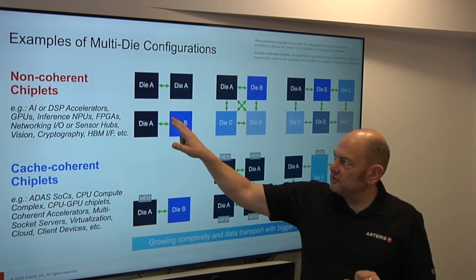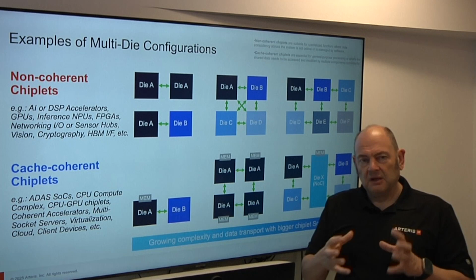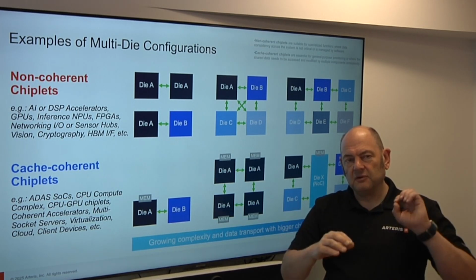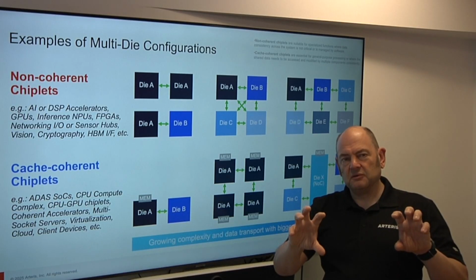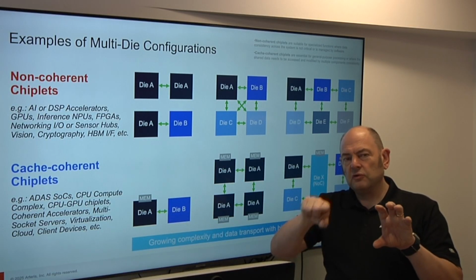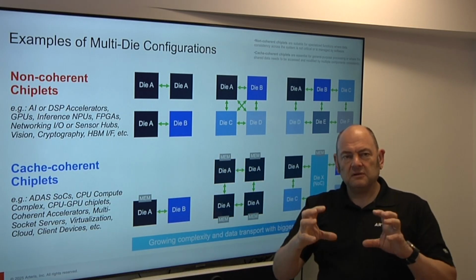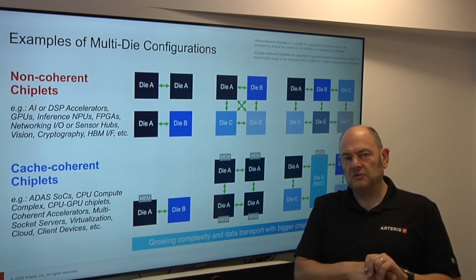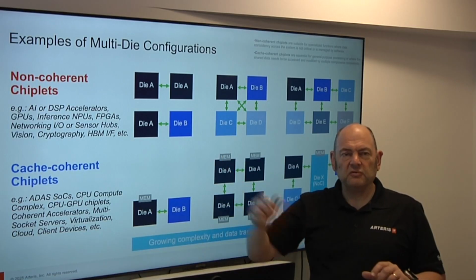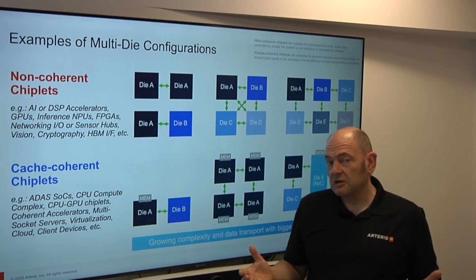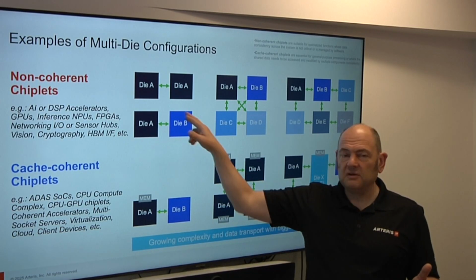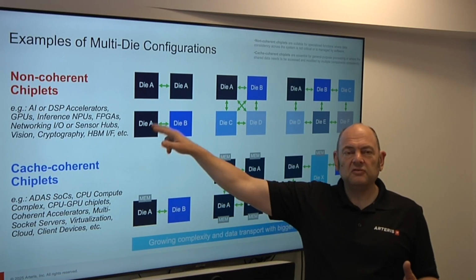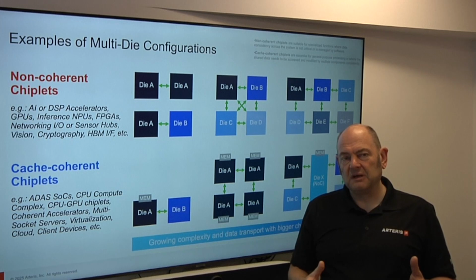But the crucial point in terms of the flow, what's changing, is that inter-chip validation has to layer on top of that. So one SoC is validated, the other SoC is validated, but the crucial thing in the middle here is the connection interface. The specification between the two has to be understood. The workloads have to be pushed between the two. Things like the memory map have to be considered across dies now. The registers, of course, for configuration of the different dies have to be known and managed and validated.